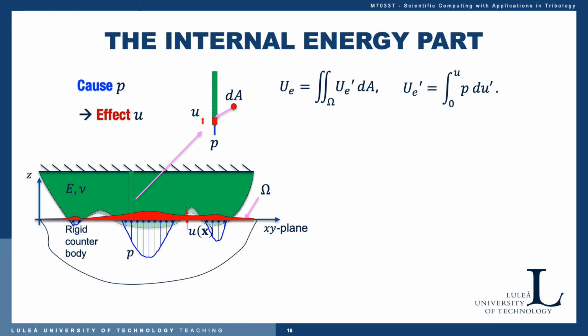At each point in this xy plane, the elastic surface energy is given by integrating the pressure over the distance of deformation. So the integral of P from 0 to U du prime. Now we have to be a little bit careful here because of the linearity. P and U are linearly related.